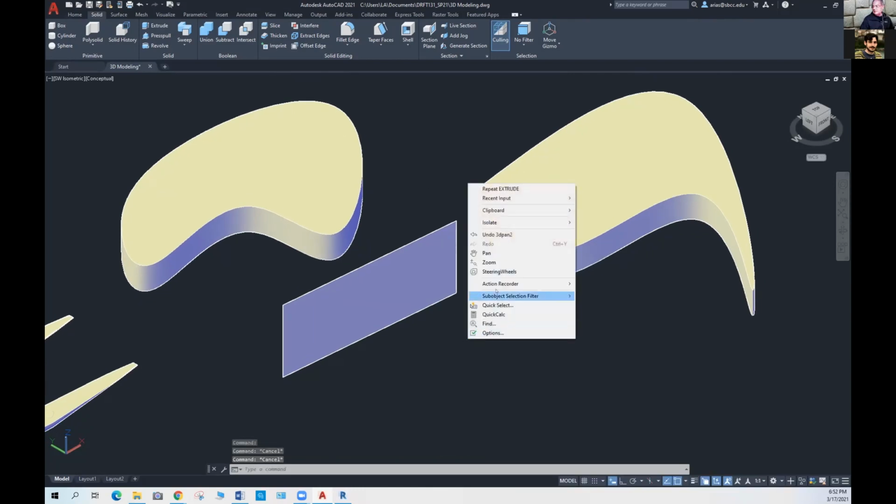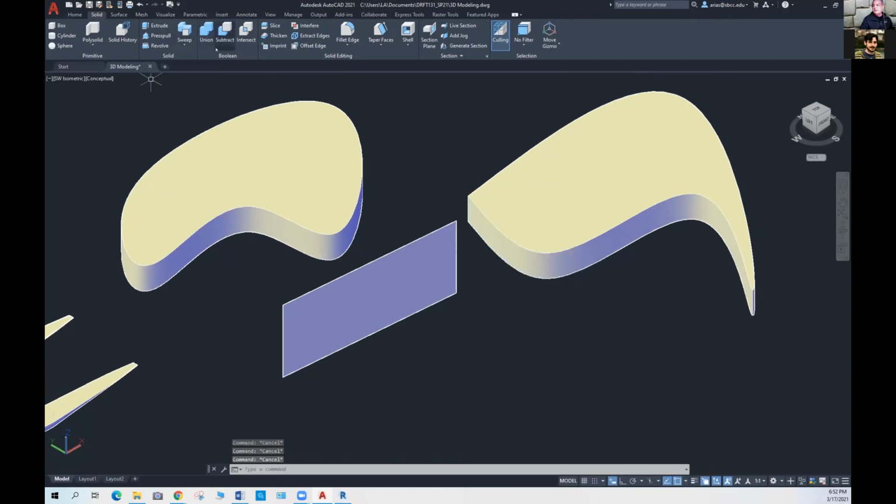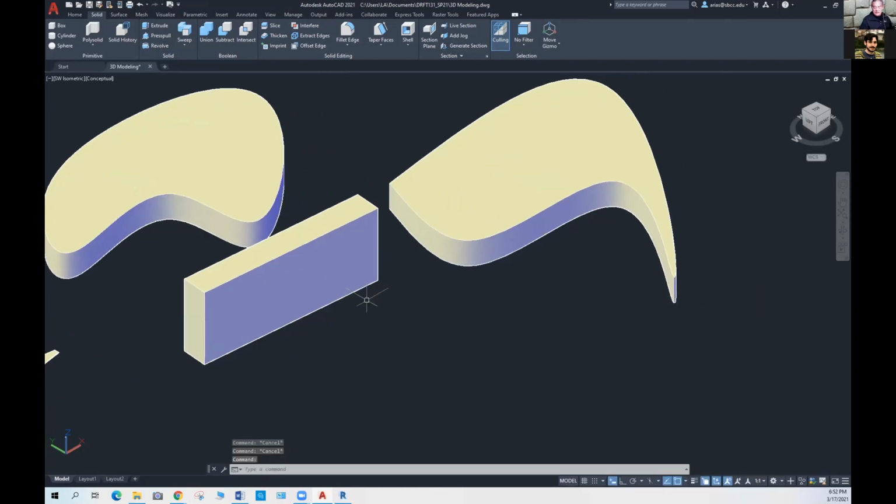Now let's see if I can apply that here because I don't remember if I can. And yes, we can, see? So we can give a thickness to a surface created with a simple line. And so very useful tool because in some cases, if you wanted to create an extrusion out of that particular line, you would not be able to do that.